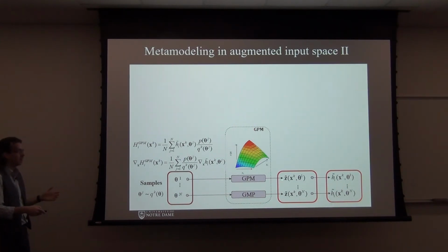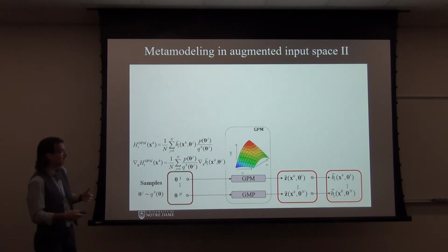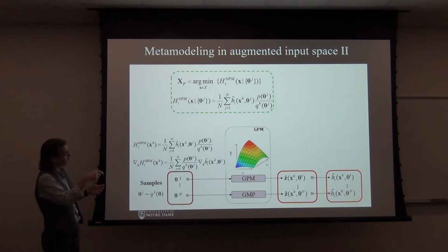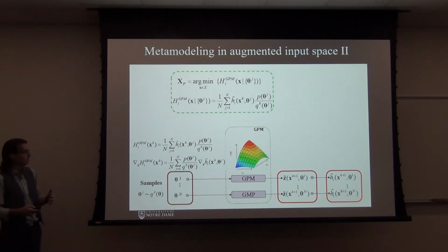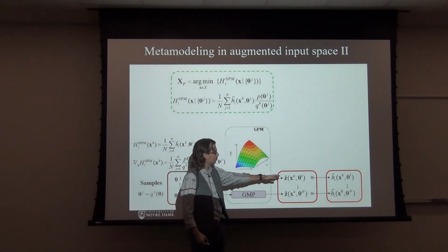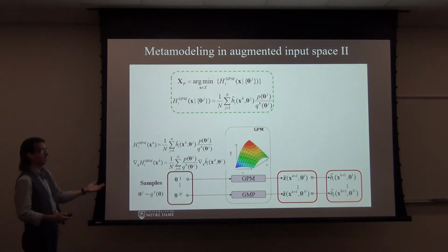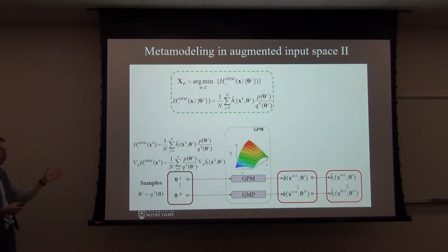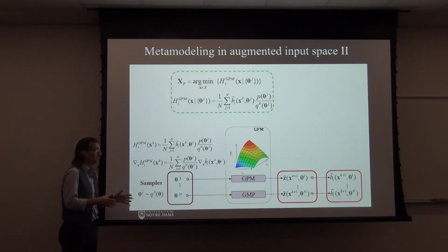And each single time that the design solution you're trying to investigate changes, you identify the Pareto front using this JPM approximation. And the trick here is that whenever you investigate a different design configuration, you still rely on exactly the same meta model, because you developed that meta model looking at variations for both x and theta.